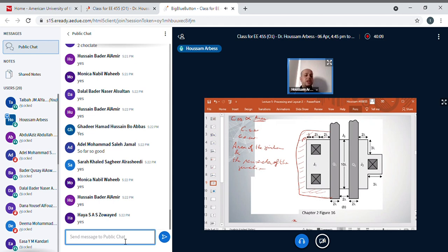I think you know how to calculate the area of the junction. If you have a junction like that, how to calculate the area? Well, if this one is the width, this one is the length, so the area in this case equals the width multiplied by the length, correct? Regarding the perimeter, it's needed to calculate some capacitances. And these capacitances exist only here, here, and here. They do not exist on the channel side.